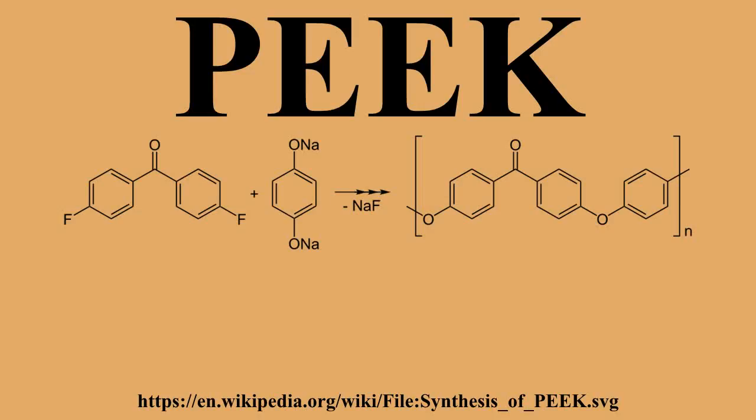Polyether ether ketone (PEEK) is a colourless organic thermoplastic polymer in the polyaryletherketone family, used in engineering applications. Synthesis. PEEK polymers are obtained by step growth polymerization by the dealkylation of bisphenolate salts.